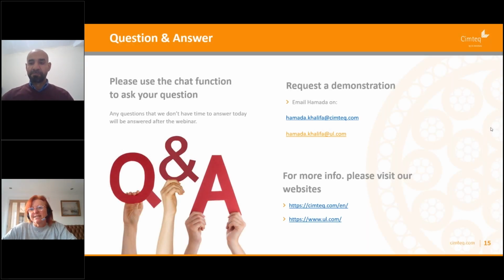In terms of the quality management system for the product, when a bad quality product is produced, we should immediately detect it, because whatever the quality plan is for that product, we should know what defines a bad product. Say it's out of diameter, the diameter gauge will flag that, and MES will then flag that we're making bad product. If something to do with the machine causes this, maybe one of the temperature controllers has gone down on an extrusion line, then if that eventually leads to bad product, we will detect it through the measurement systems on the line.